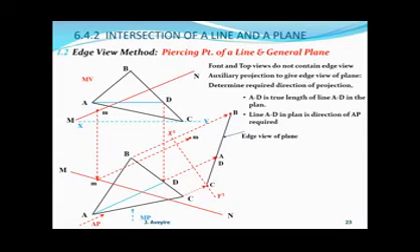Likewise, we locate a point again on the front view, N, small n, and we determine its location on the line in the top view, and that is N. Now we apply the auxiliary projection AP to it, and that is here. And we go to the front view and look at that perpendicular distance positive in X from the XY axis and bring that distance in. So we have the 2 points now. We can join these 2 points, and that is the portion of our line that we have drawn.